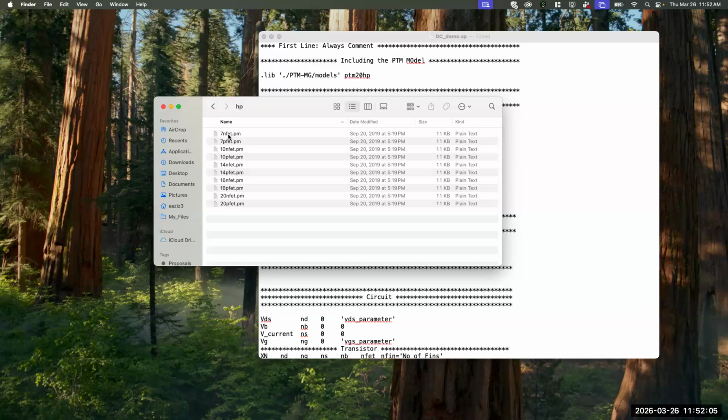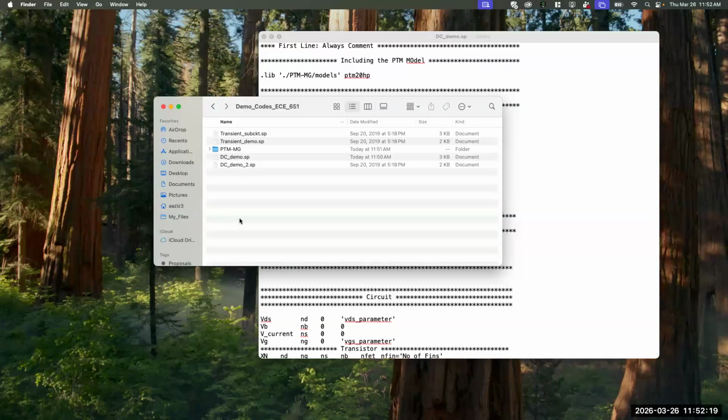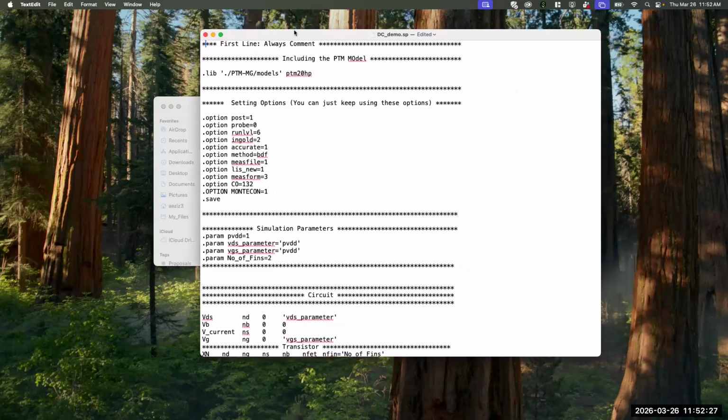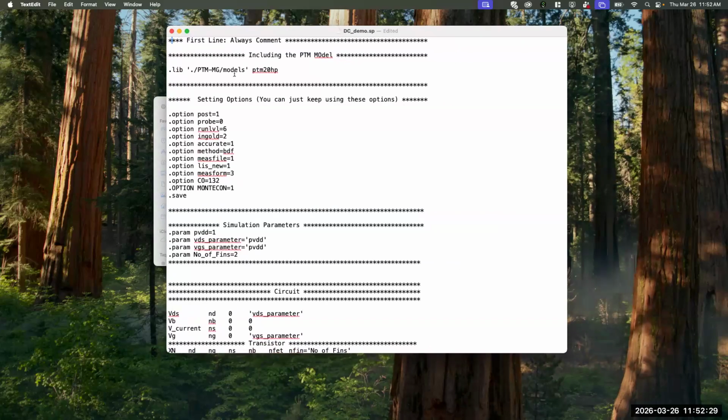Okay, and you have NFET and PFET, NFET and PFET. So N and P for both. As simple as that. But we will never have to touch them unless you really want to. And by the way, I don't recommend it, because if you change a parameter, you get something. That's the danger with simulation. It will show you some numbers, but they may not make sense because they are not calibrated properly. Okay, so now, assuming that you can now change the model parameters, we start with setting the options.